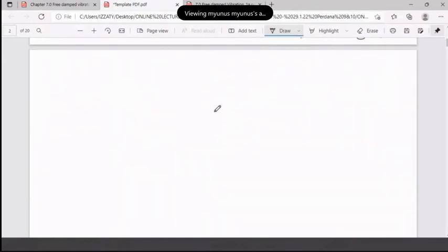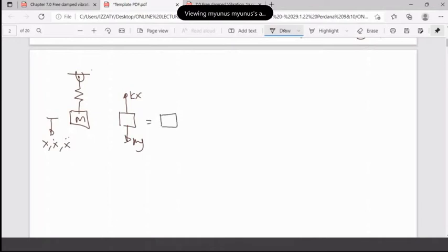What you have learned earlier was that it doesn't matter whether it is supported or suspended. For example, here you have the spring mass. Then you have the free body diagram. Remember, you displace the mass with x dot, x double dot. What you have is kx, and this one is mg, and then mx double dot. Remember the static, mg equal to k delta, and this one is basically x plus delta. You remember in our work earlier that the mg will not be in the equation. Finally, you can basically ignore the mg because this is due to statics.